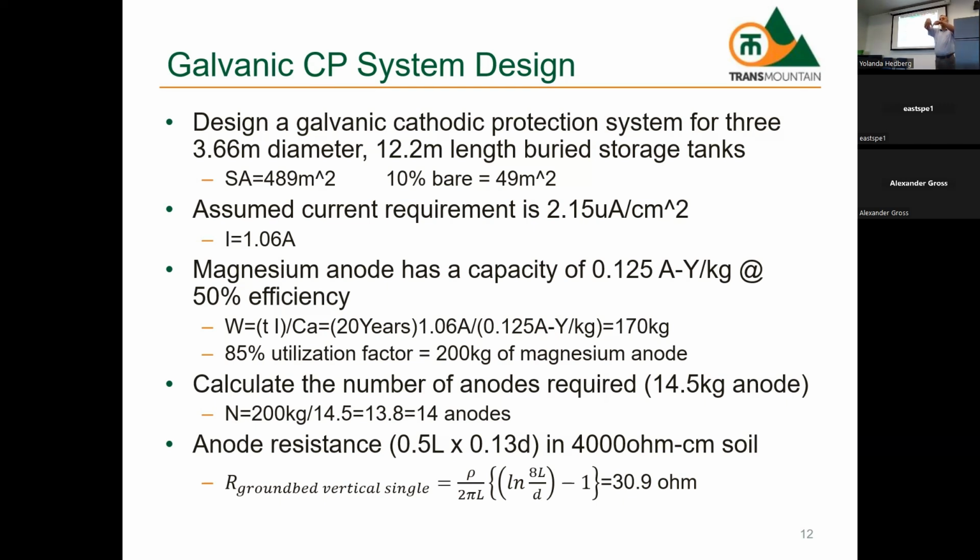You inject a current into the soil through this outer pin. It goes through the soil to the other outer pin. That's a current. The two inner pins measure the voltage that's created in the soil from the test current. The four pins are spaced equidistant apart.